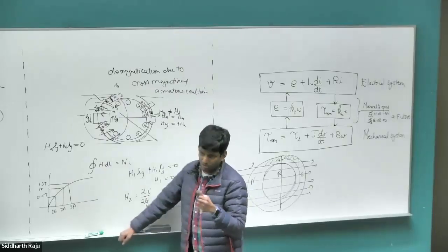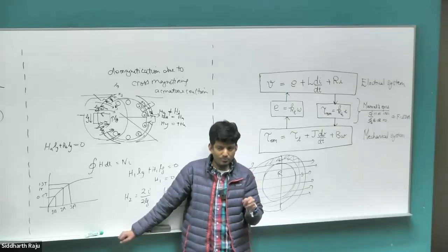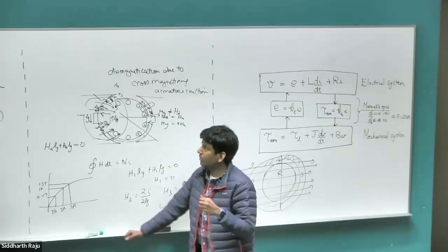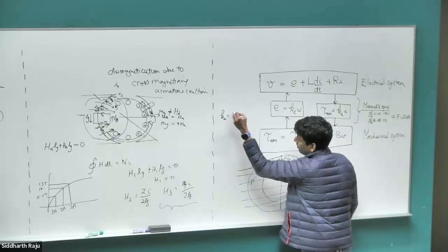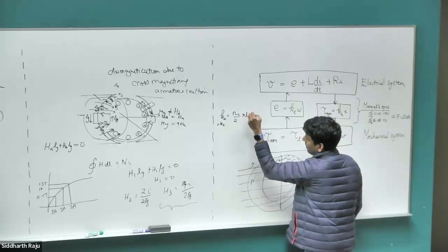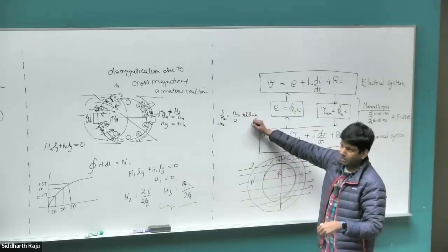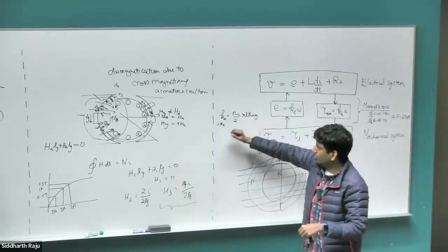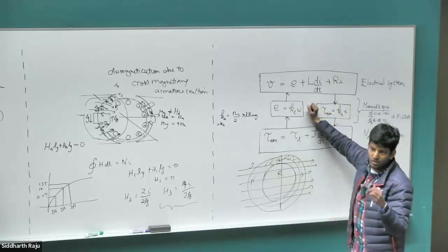Okay, what is the problem because of this? What would happen in the motor because of the reduced magnetic field? What do we lose out on? The torque, right? So this expression that we derived last class, Ke, which is equal to Kt, Nc divided by 2 times R times L times B of the magnet. Right? This B value is starting to reduce. So if this B value reduces, the Kt value reduces. So for a given amount of current, the amount of torque that the motor can produce starts to fall down.